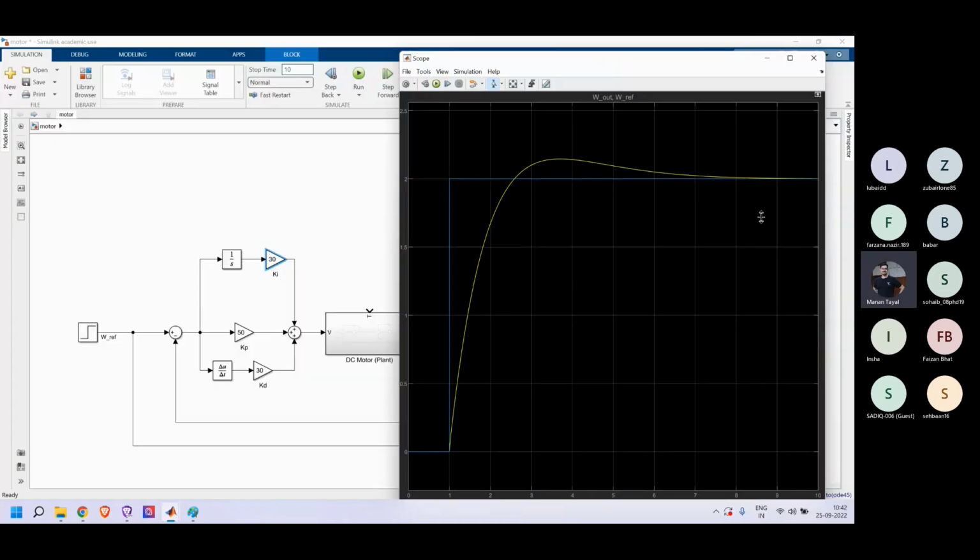So yeah, you have to change a few parameters here and there, and you have to get a good signal which has a very low overshoot, but we also want a quick rise time and a quick settling time as well, plus a signal with very few variations, right?